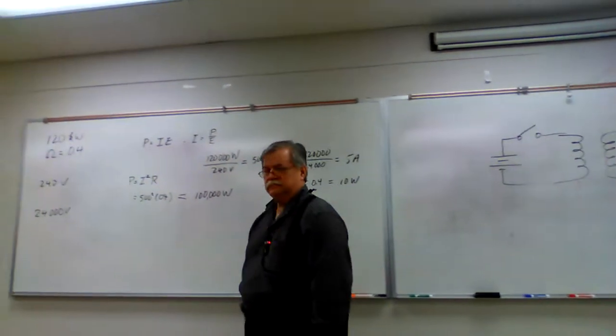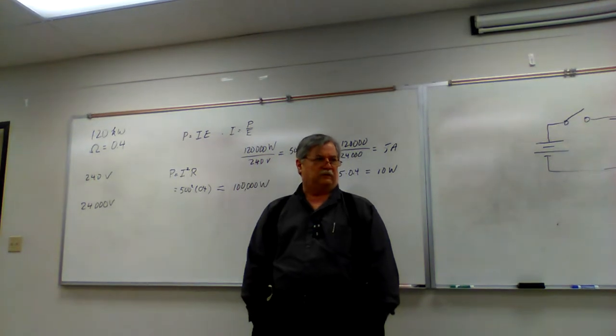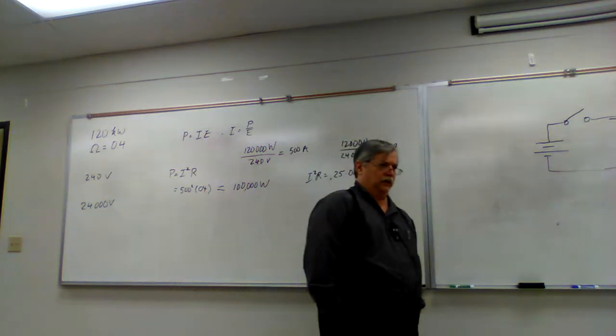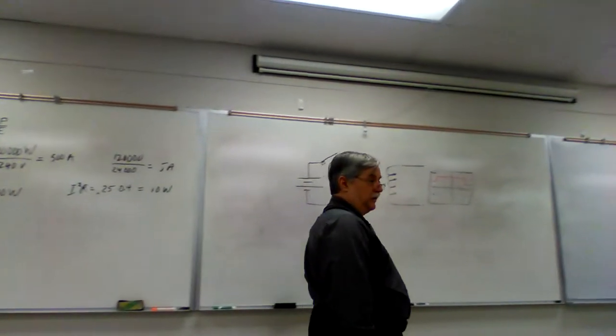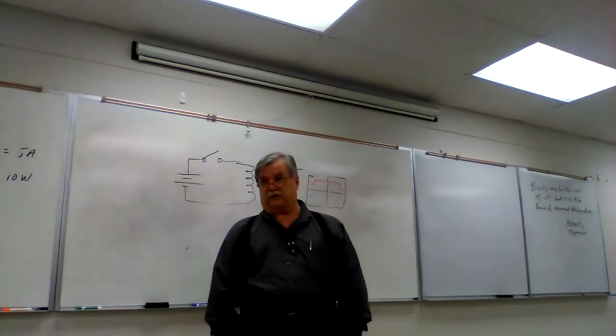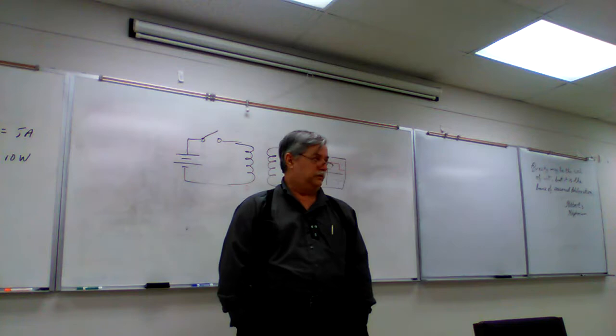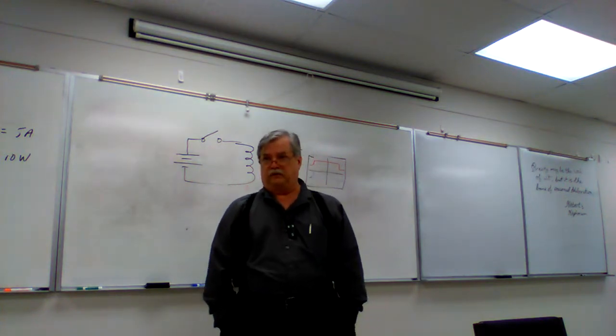But you also have to be aware that if you make the wire too thin, infinitely thin, you're going to start increasing resistance. Of course, before that happens, you're probably going to saturate the core, at which point you've pushed it too far.